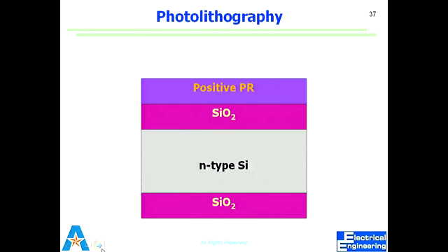We make a big puddle of that resist. We essentially cover the whole wafer with that puddle of resist material. It's liquid. So once I spin it at 4,000 RPM for 40 seconds, the thing just flies off, and it leaves behind a very thin layer of resist.